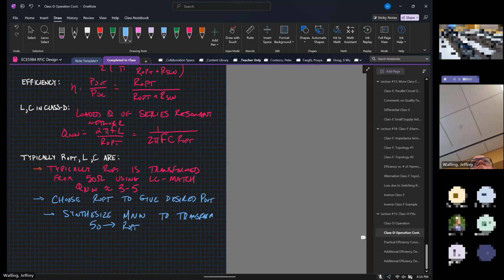It's not intuitive. So really, it's that you're not dissipating energy in the network. Q is a ratio of how much energy you store to how much power you dissipate per cycle. So it's just saying that every amount of energy going into the network is going to be able to be transferred out, at least at some frequency. That's what it means. The lower the Q of the components inside the network, the more loss happens every cycle, and that just gets turned to heat.